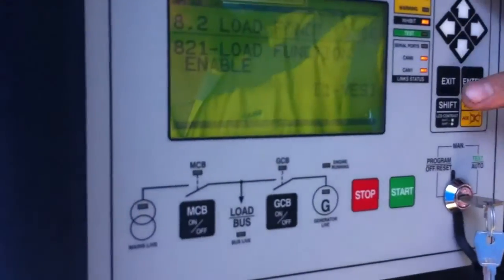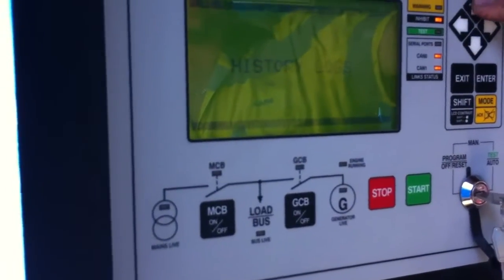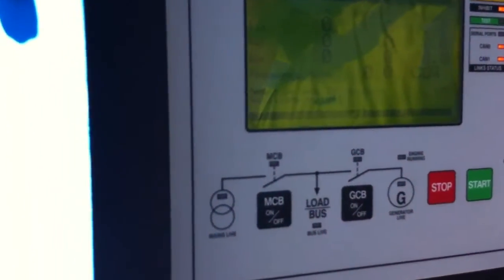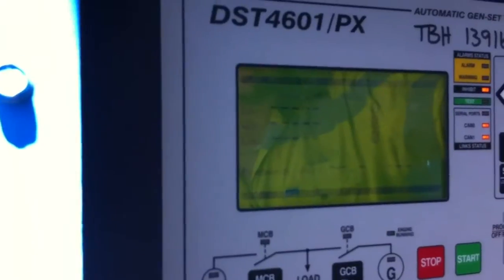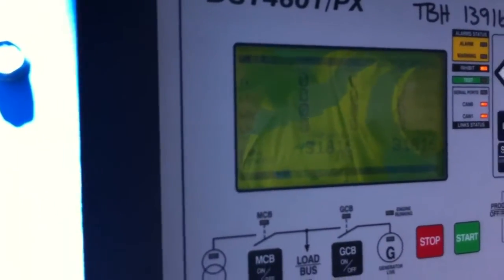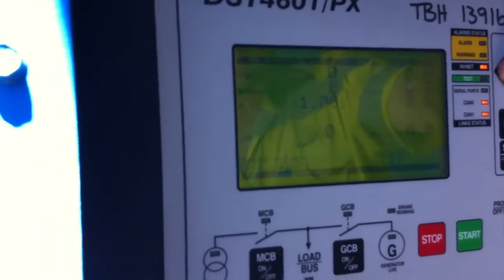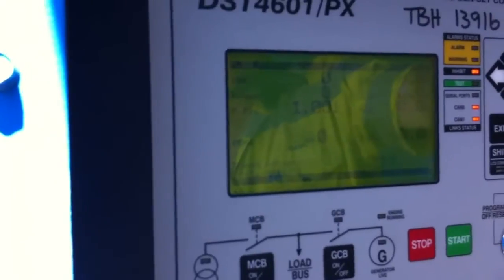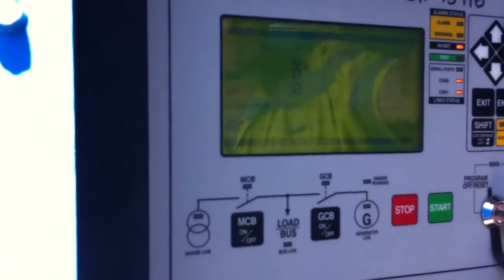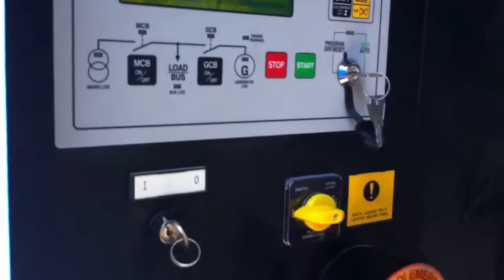So basically you go exit, everything is in. Exit, so go back to that generator screen. Now just scroll sideways, and then you can see a couple of different readings. You can see some mains readings, which aren't active. Power factors, keep going. Synchronization, you can see it when it synchronizes. Parallel function, that's when you can see it when it's in parallel mode. And then back to the generator. Okay, so now that's in, we'll just leave that for the moment. We'll set up the other generator.